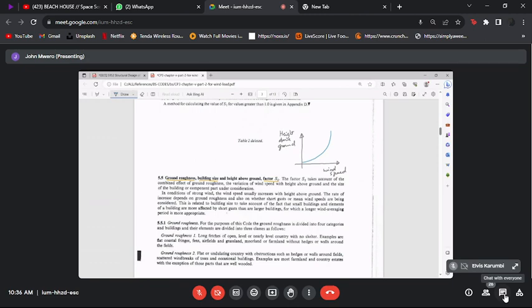So this standard that we are looking at does not have this curve, but if you pick the newer standards like the BS 6399, or if you pick the Eurocode for wind loading, if you pick the American standard for wind loading, they actually present a curve like this to say this is how generally the wind would behave with height.